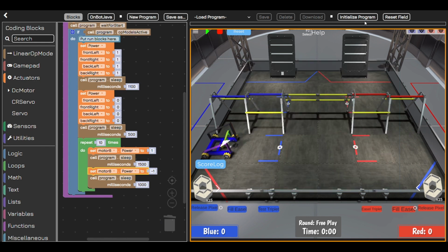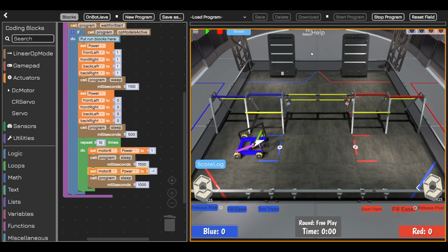Finally, the motor tilts back up by setting the power to 0.5 for the same adjust time period. This sequence tilts the launcher down then back up again by a small amount to alter the angle of the airplane after it has been thrown. Modulating the tilt duration gives precise control over the plane's pitch and roll in the air. Motor 8 provides an additional level of control during flight, complementing the launch function of Motor 7. Together, these motors allow the bot to precisely guide the airplane's trajectory.